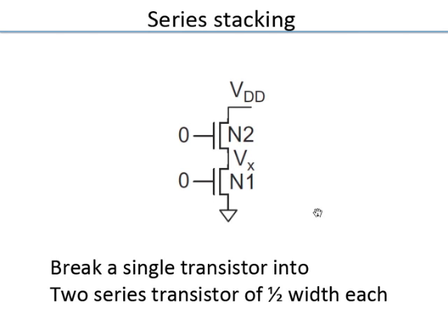And we saw how in the case of a NAND gate, which has two series NMOSes in the pull down stack, the lowest leakage happens when both the NMOSes are off. There are two series devices, so there is the effect of stacking. If there is some small leakage current going through, there will be some voltage drop across N1.